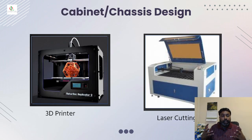Then we talked about safety in the first session. Every circuit or every PCB has to sit in an enclosure, as a chassis or a cabinet design. If it's only a prototype model, then you can just use a 3D printer and mold it with that, or a molder will do it. But if it is a much bigger, more complex design like an FPGA, where more BGA is involved, then another option is laser cutting using CNC, which gives fine, precise cutting. Again, you need to take the cost into consideration. That's a bit expensive to do with CNC machines.